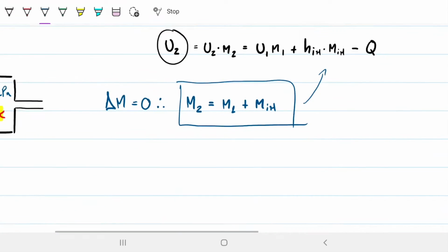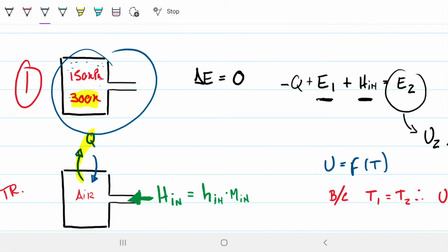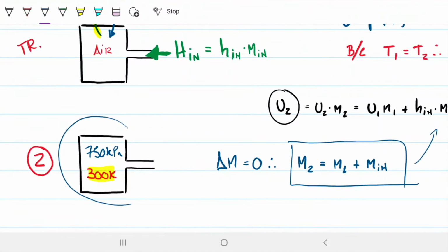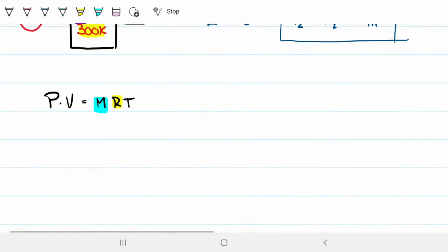All right. So this is an ideal gas. We have everything we need to be able to find the mass on the first state, and everything we need to find the mass on the second state. We can do that fairly easily. Let's go ahead and do that. So for state 1, remember that ideal gas means that PV equals mRT. This m can be for mass or for number of moles, depending on the unit you're using for your R.